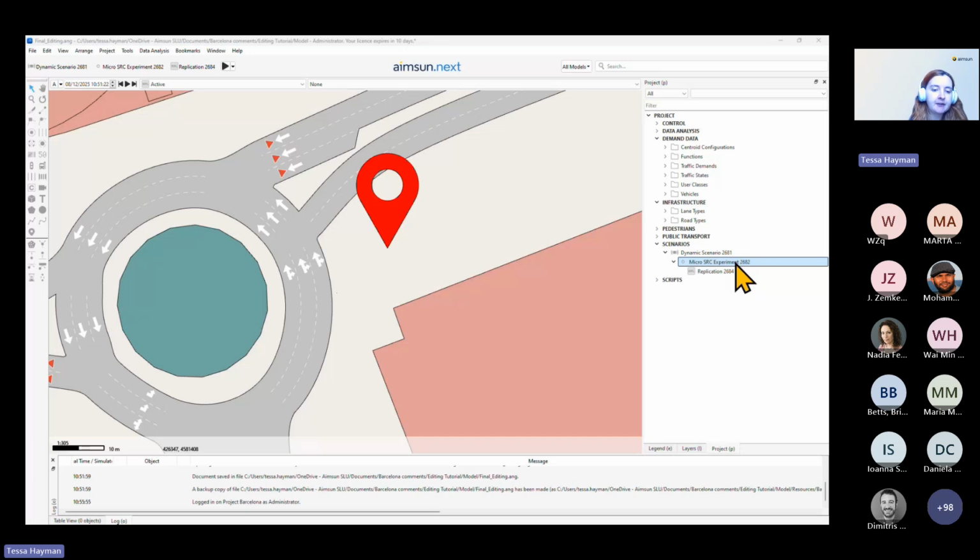I'm now going to create a new error. So I've just created a section without any connection. As you'll see, it doesn't pop up straight away. With the new check and fix, you need to click check at the bottom of the window to get it to recheck. The reason for that is that you'll see it now says new. We've got a permanence in the check and fix so that it can see whether it's got new or old problems. You can then show the discarded, and you'll see that it's also got a green tick next to it because we've fixed this error.